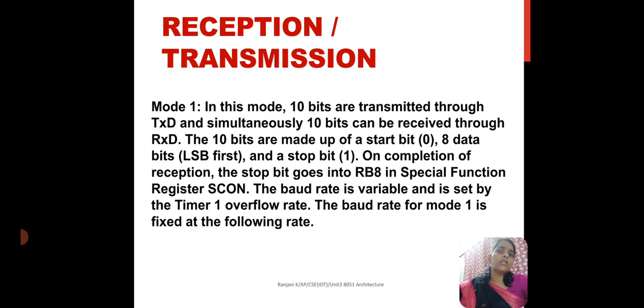In mode 1, 10 bits are transmitted through transmission, and simultaneously 10 bits are received through reception. The 10 bits are made up of a start bit 0, 8 bits of data, LSB first, and a stop bit of 1 bit.